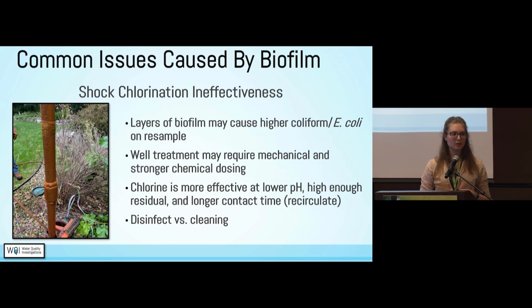We found that well treatments are a lot more effective if there is a mechanical aspect to help remove some of that material first. Not only does it make the chemical more effective, but it also makes the chemical dosing potentially less, and you use less chemical. Chlorine alone is something we found is not effective in all cases.